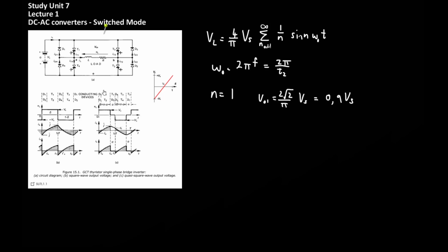So for example here, in the first part of the cycle, T1 and T2 are on as in the bipolar case. But before the second part of the cycle, there's a phase where only T1 is on and the other thyristors are off, and D3 comes into play to conduct current back to the source. This can then be expanded to get a dead zone by only allowing D3 and D4 to conduct, and finally to get the lower part of the square wave, T3 and T4 conduct, and by repeating what was done initially, the upward step of the quasi-square wave can be generated.